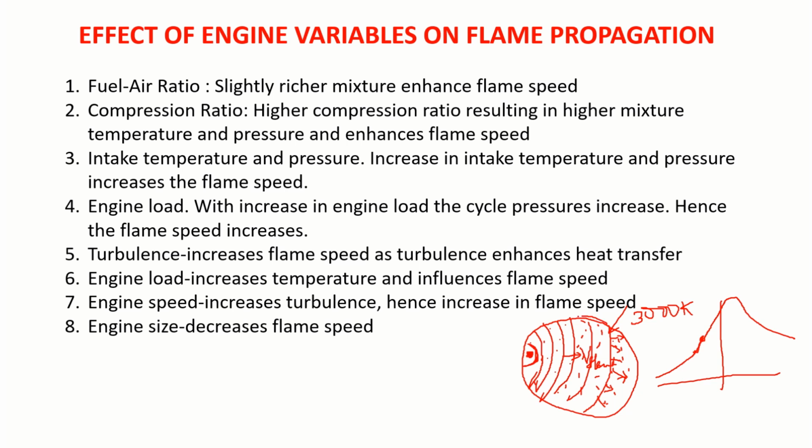The second thing is, here you have burned gases, so the volume increases and because of that it starts expanding. It will compress this charge, which I call the end charge. This end charge is receiving heat because of this and is also getting compressed. And there is a chance that the end charge might auto-ignite.